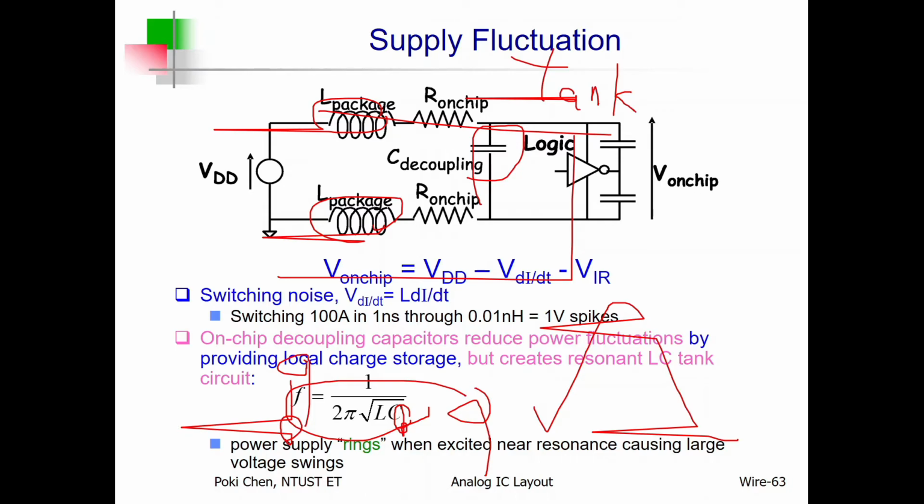Okay, between the VDD and the ground. Resonance for the VDD and the ground means what? They are not DC values. No. You will see some kind of fluctuation according to such kind of LC tank resonance. Wow, it's really harmful for your chip operation, right?